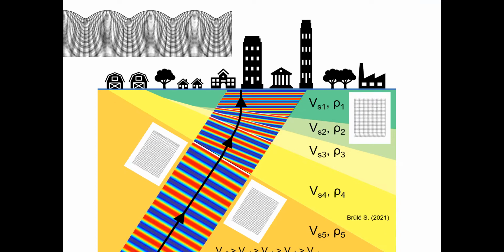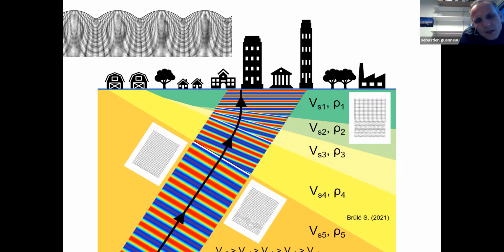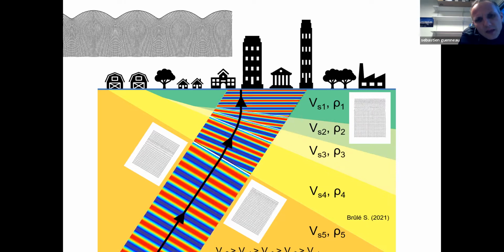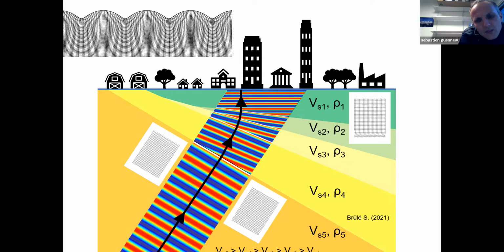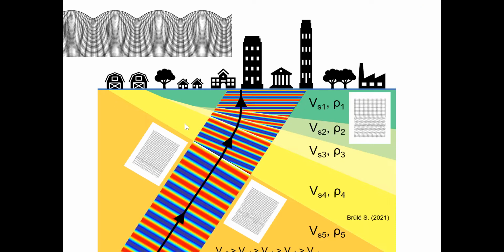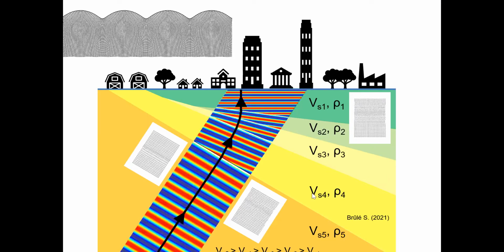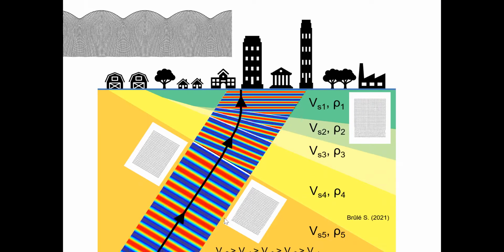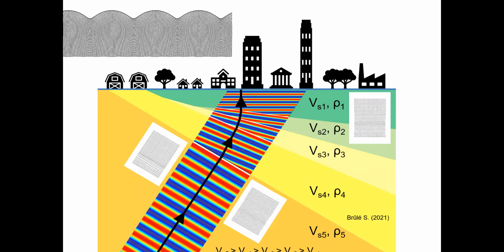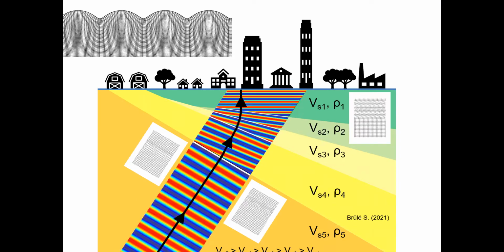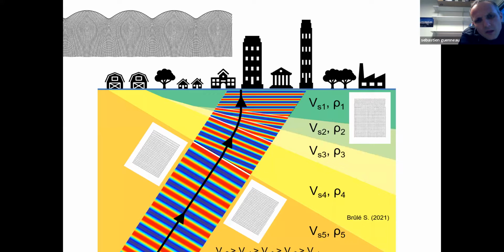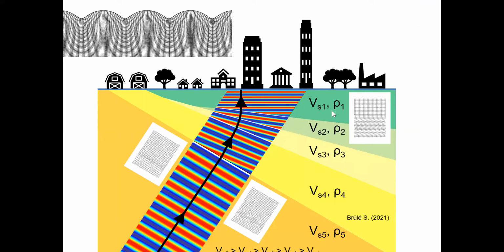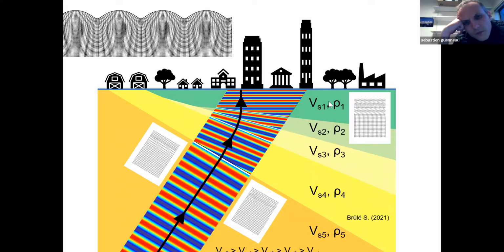Yeah. And so here, do you consider that the basin is just the green area, or is it all the layering? What is the basin here? Oh, the basin here is the yellow one. It's coming from number 4 surface, for example, because here we have an incident wave. You can consider that this is the seismic substratum. Yeah, seismic basement. So it's a rocky ground. So we are progressively going to soft soil at the surface.